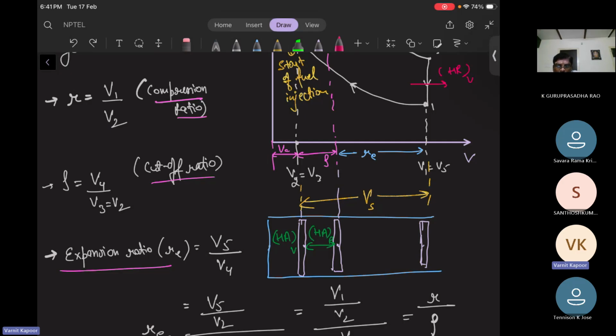So I was saying that in the petrol cycle, the maximum temperature is greater than in the diesel cycle. Why? Because the self-ignition temperature of petrol is high. That's why you need an external spark for the fuel to burn. In the petrol cycle, the net heat interaction equals the net internal energy, because work done for a constant volume process is zero.